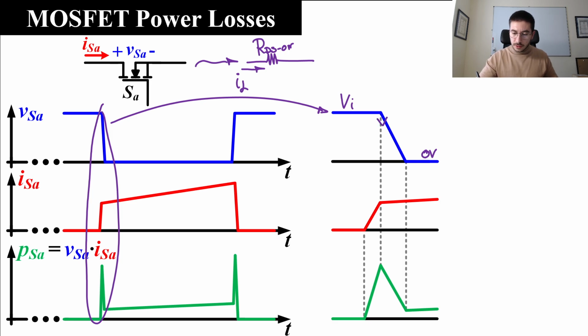So when we turn on the device, the voltage goes to zero. And in the case of the current, here we have 0 amps, here we have the inductor current value in the transition. In fact, here is the minimum current value through the inductor. And since we turn on the device, from 0 we go to that level.